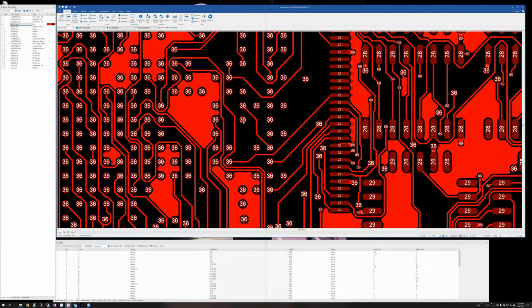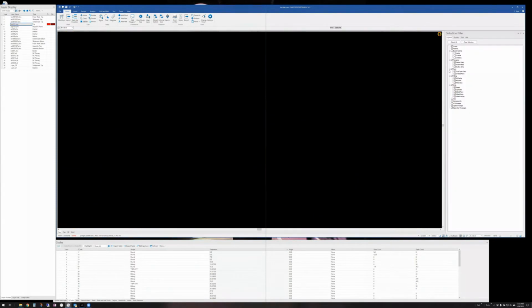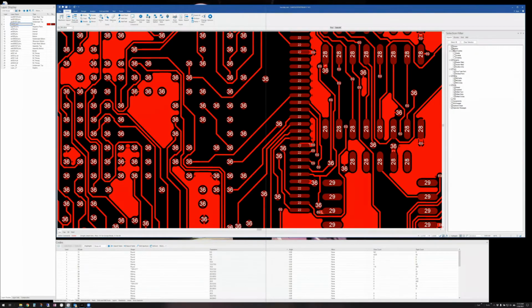Flash and draw, I think you understand that, but it is in this question here. So when I'm in any of these edits and I get that filter over here, let's just go back into delete, for instance. You'll notice at the highest level there is draws versus flashes. A polygon is part of a draw, but these could be vector polygons as well. So as you can see, polygons are checked here as well. But generally, a draw is equivalent to a trace, and a flash is equivalent to a pad.